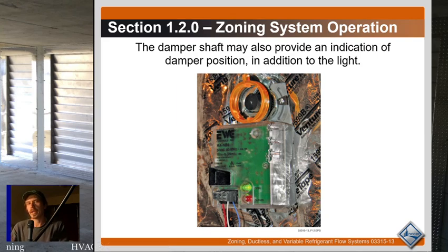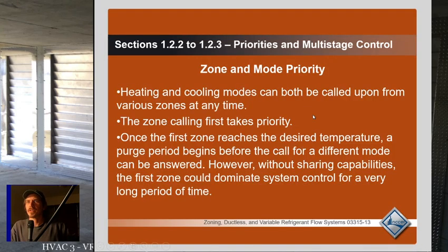So if the damper slips on the shaft, or the actuator slips on the shaft, then even though the actuator says it's closed, the damper could be open. And there's very few ways to prove that. You can do it with an end switch, but the way a lot of end switches are made, those can slip and give you a false security of what position that damper is in. So a good old black Sharpie is usually the best way to tell for sure what position it's in, on installation, or on a service where you have to disconnect it and set it back.